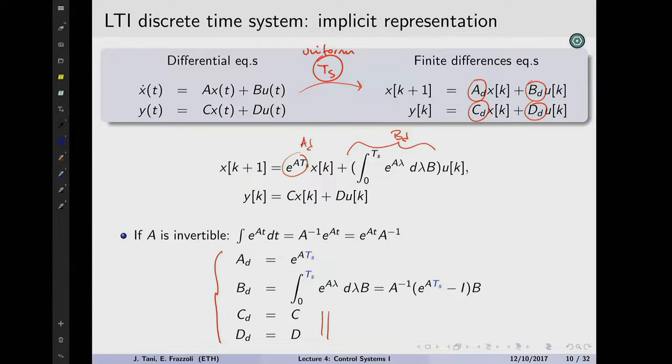So there is a very famous result. We'll not get into it, but the idea is when you sample, you want to choose a sampling period that is fast enough depending on what you're sampling. It's intuitive. If something is changing very quickly, you want to sample it very quickly, otherwise you'll lose information. If something is going very slowly, like the seasons, how much rain falls every year, you maybe sample it once a week, it's okay. Okay, so this is important. This is a way to pass from a continuous time representation to a discrete one.